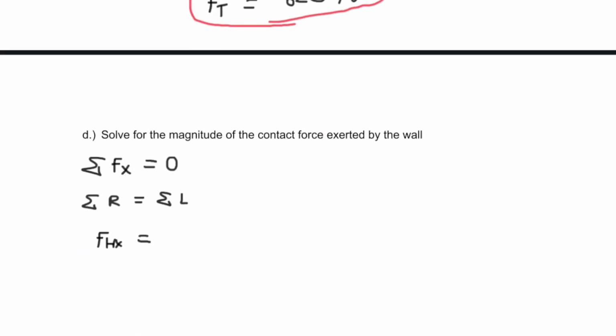So we have 620 newtons of tension, but attach a cosine 30 to extract the part that's acting in the x direction, and we get a not as nice value as last time of 537 newtons. Not our answer, because that's only a component.